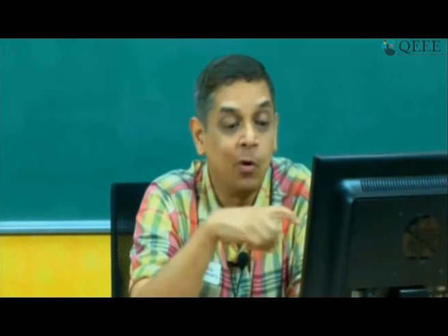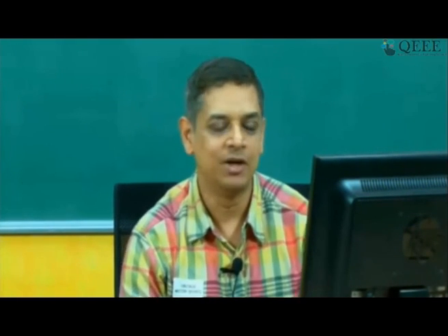So we have used for bolts and all that the shear force, Fu by root 3 in shear, and then we are trying to combine with tension, right, under combined shear and tension. So automatically in the denominator part, we are using the bolt strength, the bolt value we are taking for shear, with a factor of root 3. So that is quite similar to that. You can just work it out and you will find that it will come quite similar to this expression.